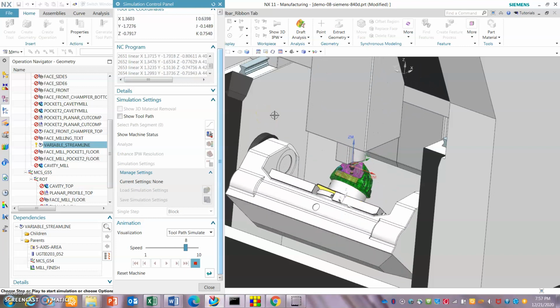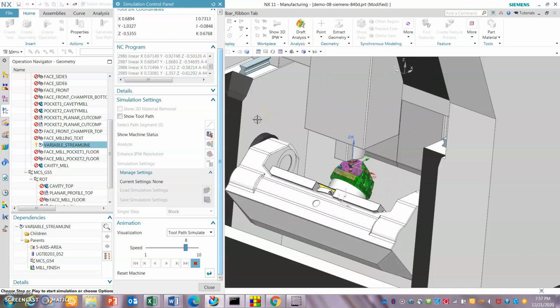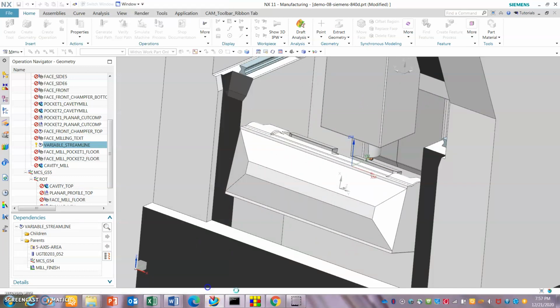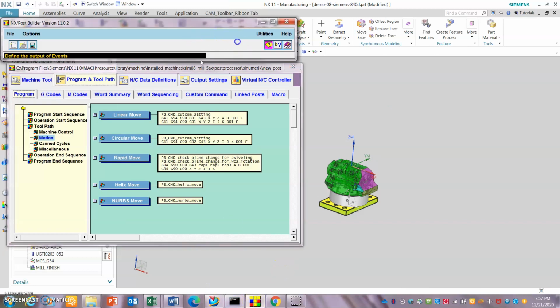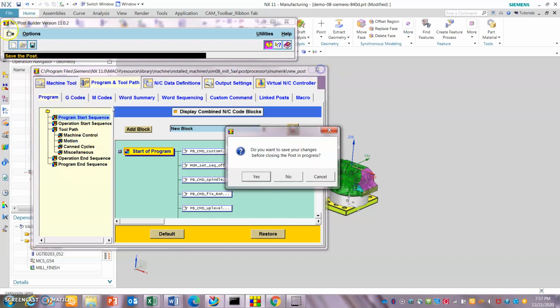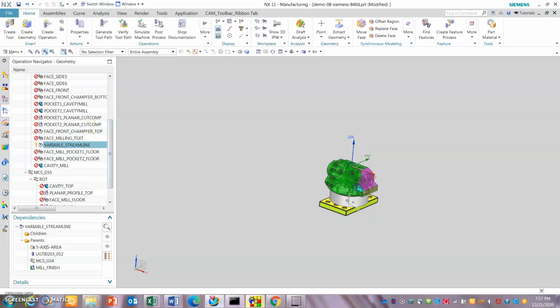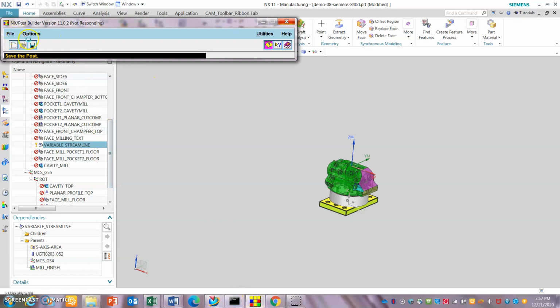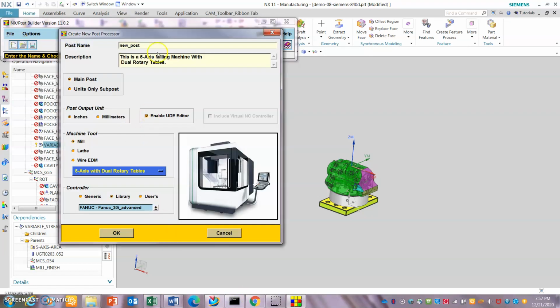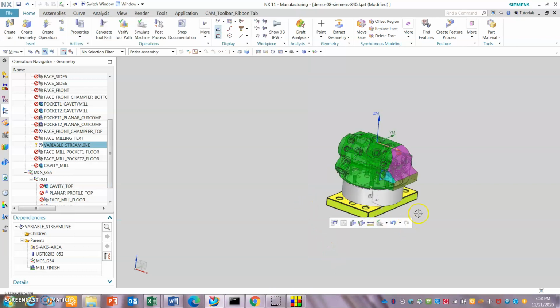Once we have all the examples of the toolpath, we need to have the post written for 3D coordinate rotation and also G43.4. We can now go into the post. Let's configure all the post settings we need. So let's go into the new post. Okay, so this video is only 15 minutes. I will come back to the second part of this one soon.